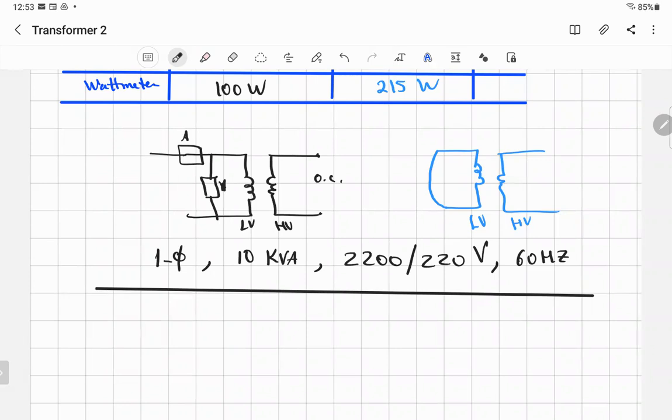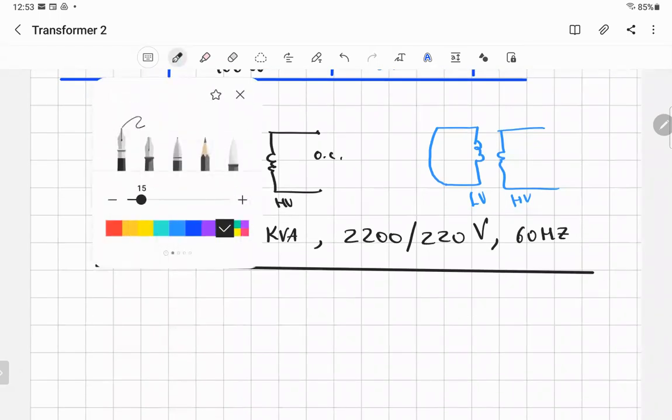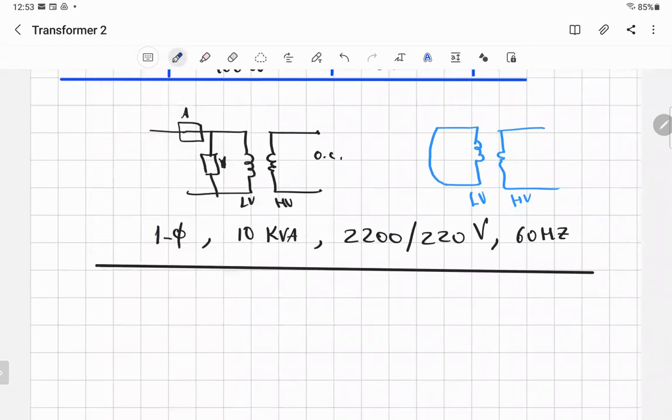And you can get from that the turns ratio. Is it the exact one? No, it's an approximation, of course, because the voltage E is less than that, but it's acceptable. That's what engineers do. So the first thing I'm going to do is get the right information.